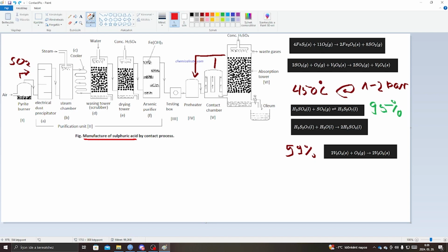You can see these little dots. These are solid layers, but porous. They usually use quartz or something like that that is porous. So as they pump the gas mixture inside, the gas rises through these little pores, and through these little holes, heads like shower heads drizzle down water or sulfuric acid. They react with the gas that rises through these little holes.